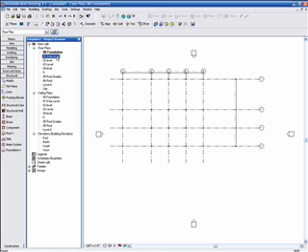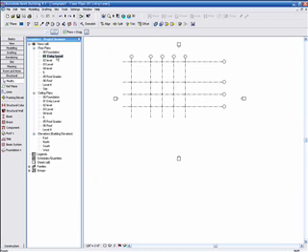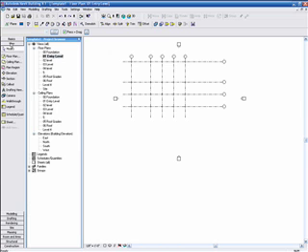So we are going to View tab and click on Camera. Okay. On the Options bar, we're going to select From, and we're going to select that default that's there as well. Okay. So now we're going to place the camera somewhere out here in this corner. So that places the camera.